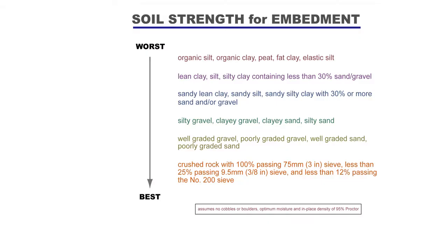To use these fill height tables, first you need to determine the soil type you will be using for your project. There are a variety of materials you can choose from, whether in situ soils or purchased materials that will be shipped to the job site. The soil that you select will affect your pipe design and installation requirements.